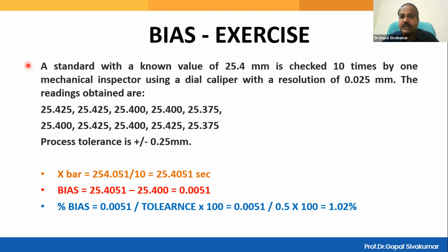With respect to the working range, if the bias is less than 10%, the industry guideline says it is acceptable. But more perfection is always better. If the bias is 0, that's the ultimate. Only to reach the ultimate, you think of calibrating your equipment. Am I right? You want to reach the ultimate, you calibrate the equipment.